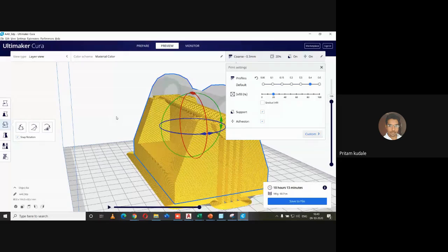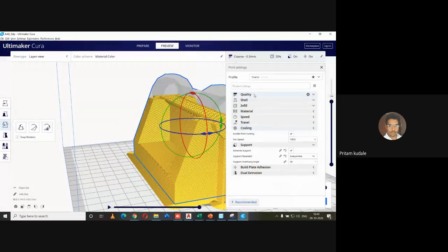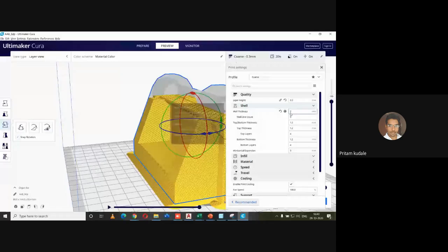Now again this angle depends on your manufacturer. Some advanced printers or high cost printers come with a maximum angle up to 60 degree also. That up to 60 degree it can accommodate. And it also depends on your mode setting, that is known as the layer height and your shell thickness.